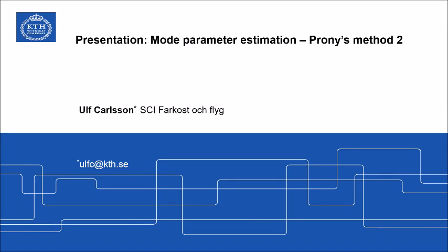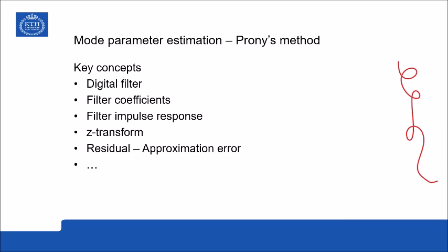In this presentation I will continue the discussion of Prony's method to estimate the mode parameters, and I will use a digital filter synthesis approach. We will meet a number of key concepts as usual: digital filter, filter coefficients, the filter's impulse response, the Z transform, and the residual, that is the approximation error.